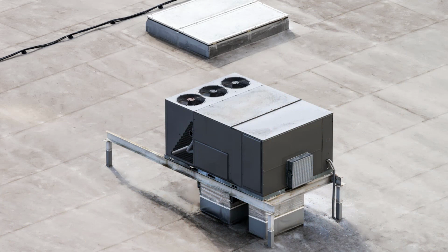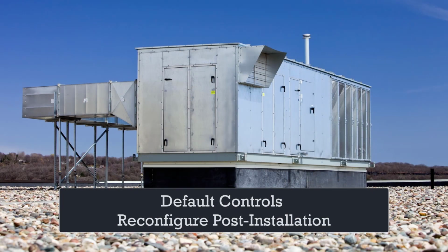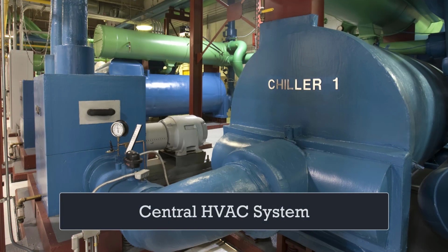In low-rise building applications, because self-contained rooftop AC units are often not fully integrated into a central HVAC system sequence of operation, control of RTU start times and fresh air damper operation is often overlooked. Rooftop AC units and associated dampers and controls are often configured with pre-programmed default controls. In some cases, the unit may have basic control points that need to be configured during or after installation. Similar to large building central HVAC systems, introduction of fresh air during the optimum start cycle typically increases recovery time and energy consumption.